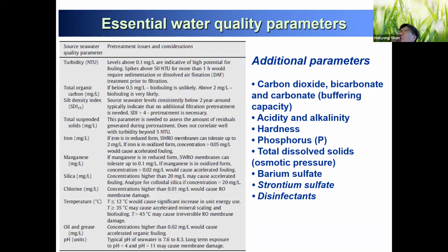That's exactly the same for water that needs to pass through your membrane. A water molecule H2O is 0.3 nanometer in size. The 0.3 nanometer size will pass through your membrane, and the sodium chloride, sodium size is around 0.7 nanometer. The water molecule will pass through your membrane, but your sodium chloride at 0.7 nanometer cannot pass through.